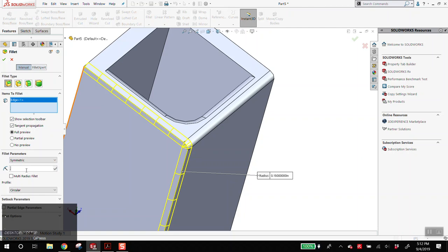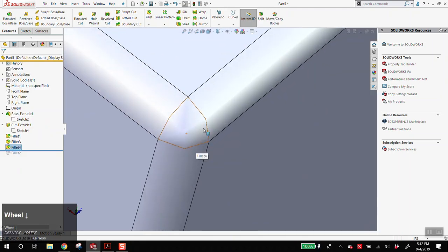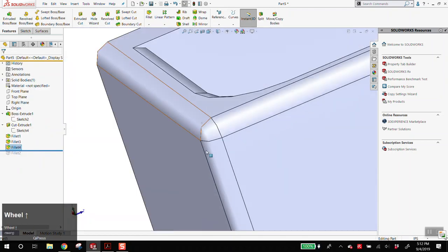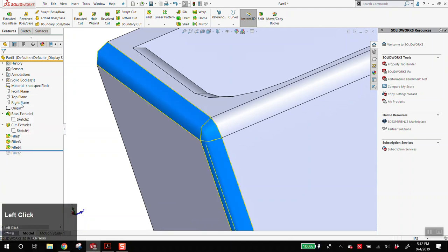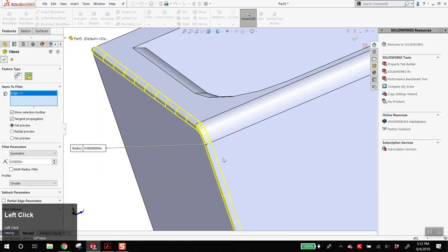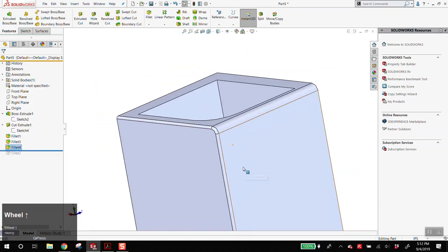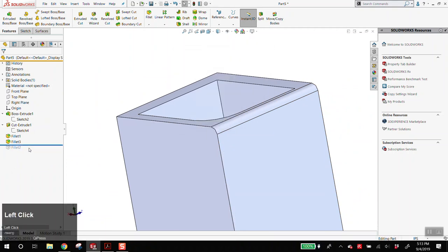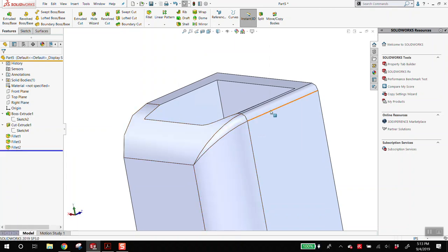So again, for some of you, this may have failed out. If this fillet is the same size and I click on this, it now just gives us this perfectly round corner. If I edit this to be smaller, like 0.05, you can see now it travels around that corner like that. If I delete this and go back down to the massive fillet I put on here, it turns it and does this really weird thing. Grimace face, it looks ugly.